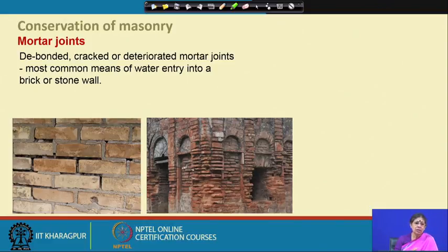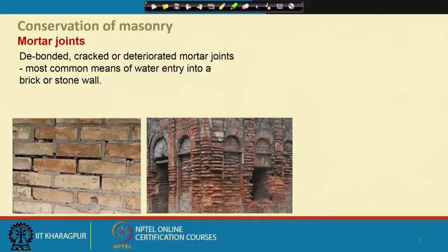So, what happened with the temperature fluctuation and other, this is strong. One has a sort of belief that if you give a stronger material for the joining, that is better. It is absolutely wrong, because the joining should hold the thing together, but it shouldn't be stronger, because in that case the original material itself, the brick, becomes deteriorated faster. The joint is a stronger material and does not behave in unison with the temperature fluctuation and other things, and it cannot breathe.